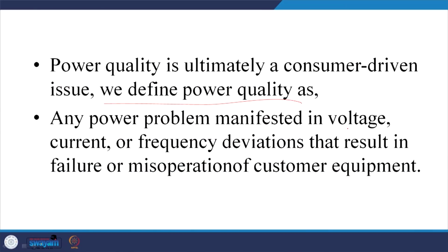I may require a particular power quality for a particular machine, and thus we define power quality as any power problem manifested in voltage, current or frequency deviation that results in failure or misoperation of the customer equipment. Then we will say that we have a power quality problem.